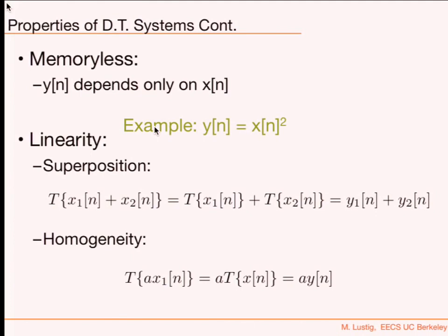We'll think, okay, we've got to be careful not to overdrive the system into a point where it's nonlinear again. You'll see that with the software-defined radios I'm going to give you. Sometimes you'll be too close to a transmitter, you're going to overdrive the system, and you're going to see lots of peaks in the spectrum, and it's like, whoa, how come there are so many peaks?